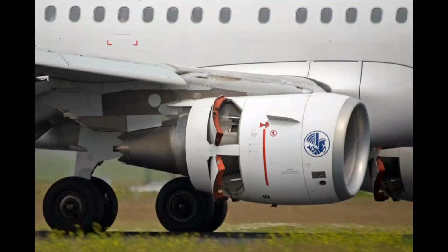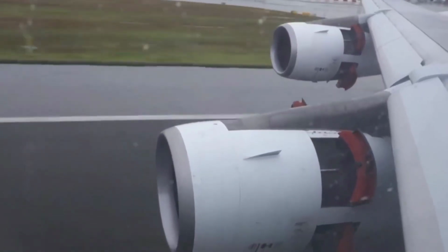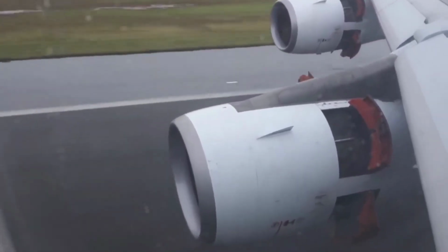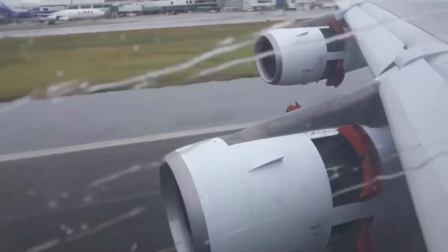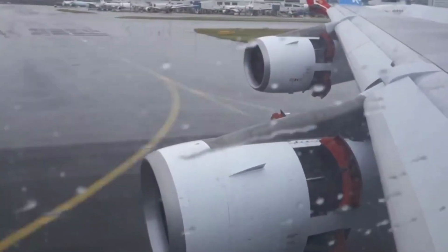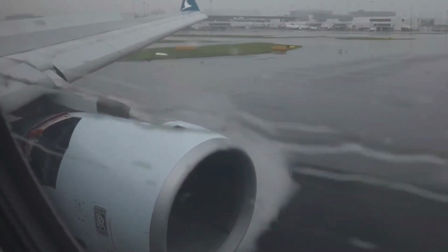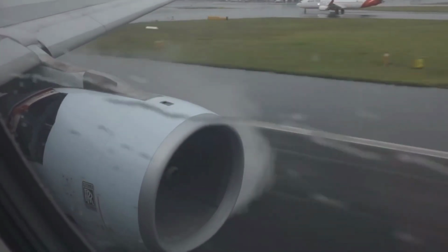Number 2, clamshell reverse thrust. The process here is very similar to what happens in the Cascade. After landing, the throttle levers are put in the reverse position. Then the thrust reverser system is activated. With that, the bucket doors are closed and 2 or 4 pneumatic actuators pivot the doors and close the exhaust nozzle. Therefore, the exhaust gas direct exit is blocked.